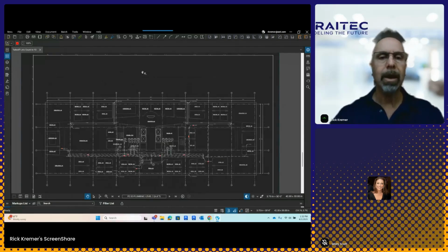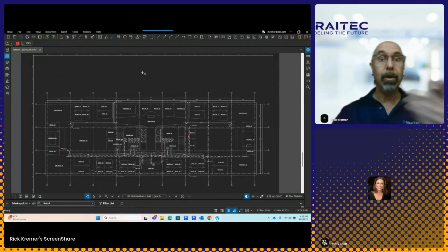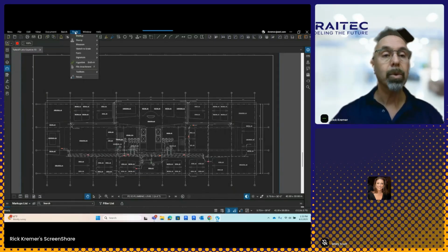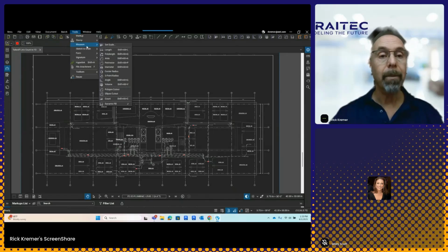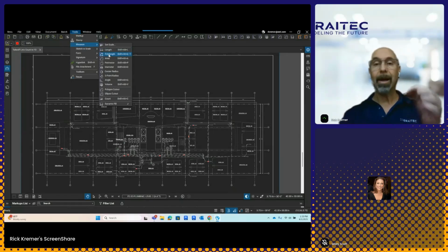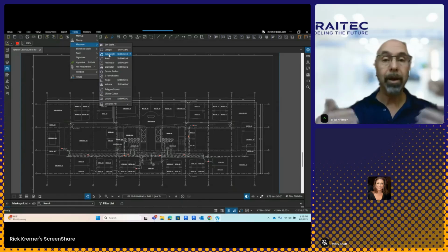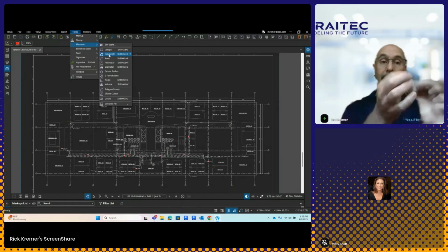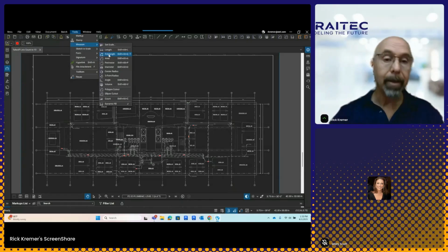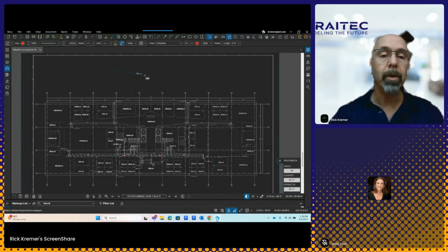So how do I do a linear calculation? First, I'm going to go over here and place a sample so that I can use it over and over again and store it in my tool sets. Okay, so how do we do that? I'm going to go to Tools, Measure, and do a poly length. A poly length is a multiple length object that could be considered like conduit or pipe or ductwork. Anything that has a start and an end and it zigzags is a poly length. And I'm simply going to go over here and draw something like this, right?